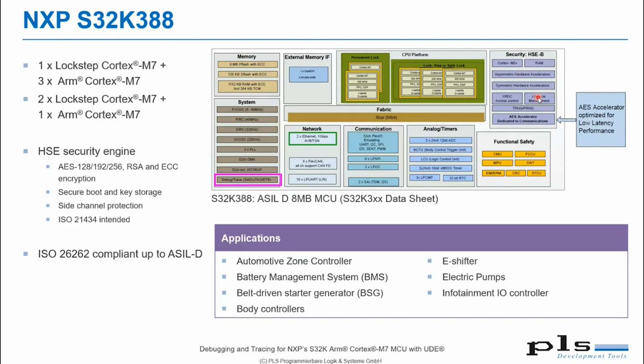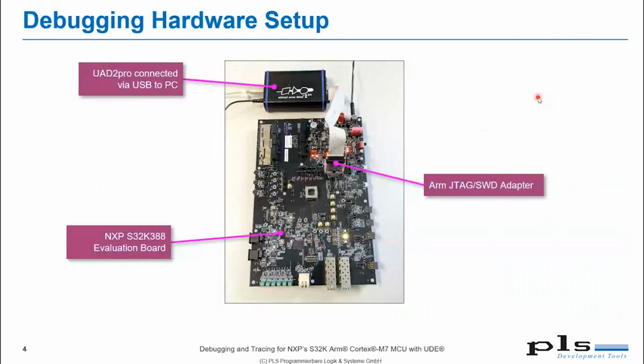And for the debug tool, the CoreSight subsystem provides hardware breakpoints, triggers, and so on. That is very useful for the basic debugging functions like breaking and single stepping, of course. And the triggers also allow a synchronization of the debug actions across the cores. That is very interesting for us. Later on, I will show you this in an example.